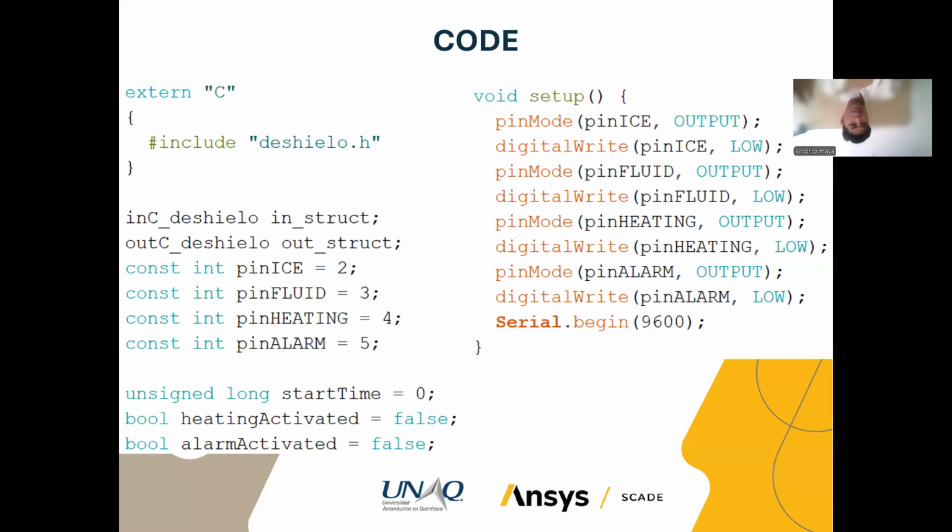A tick is a beep, beep, beep every time the processor does an operation. So the millis function takes this value, and we can divide it by 1000 to obtain the amount of seconds that have passed since the beginning of the code, or since one specific moment that we want to consider. And I'm going to use this later.